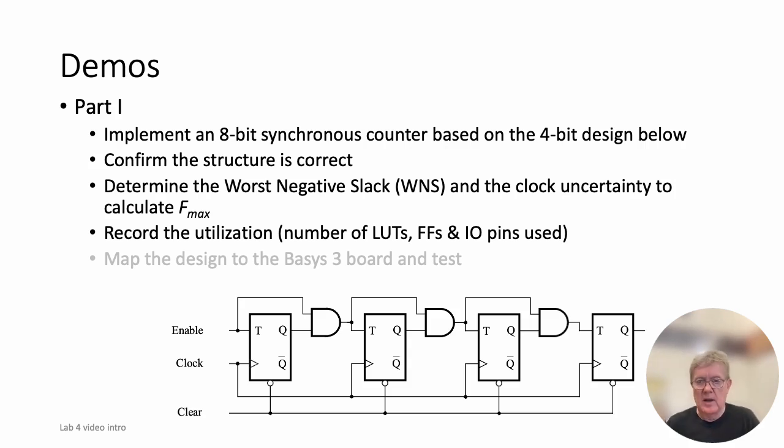That's a slightly involved procedure, and it's founded on firstly determining what the worst negative slack of the circuit is, or which path has the minimum slack available on it beyond the clock period that's available.